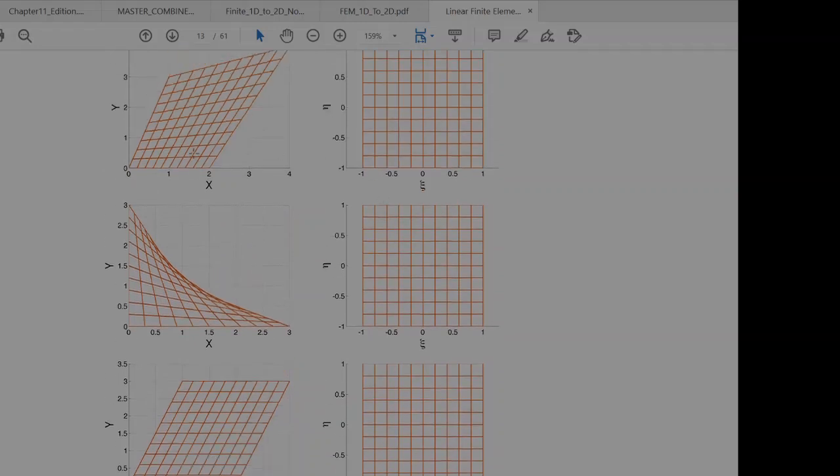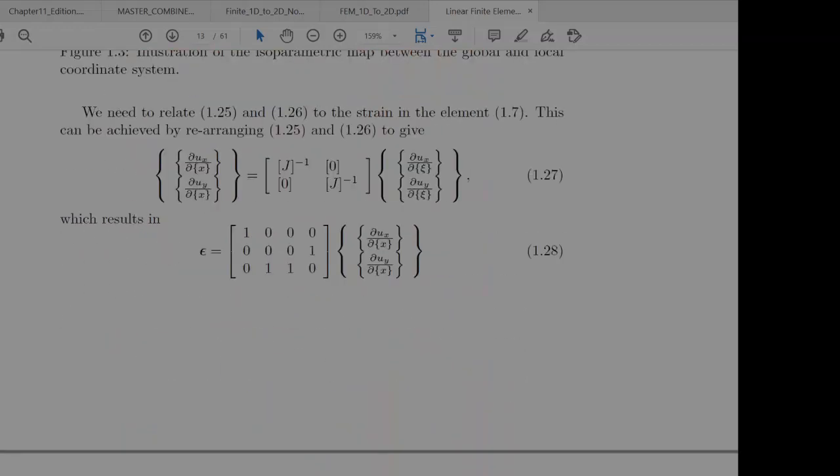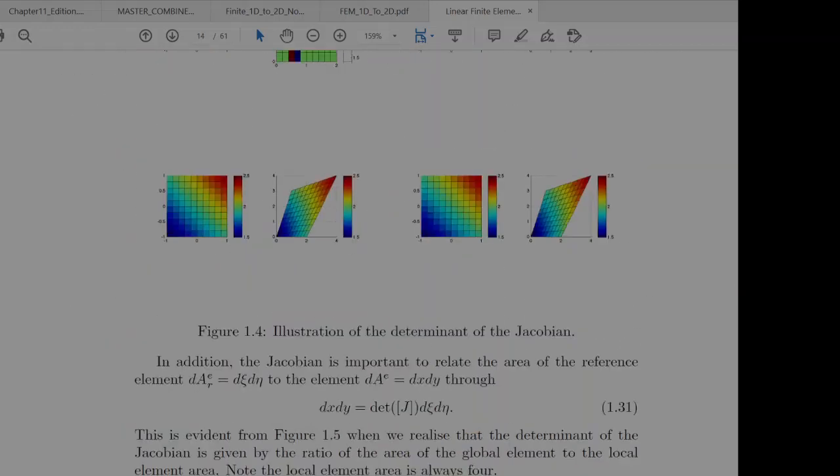Here you can see severely non-constant Jacobians, and this non-convex element is a disaster. You can see the chaos that's ensuing there: non-uniqueness and all sorts of stuff. You can't even tell which point maps from here to here. So that breaks down the mapping completely. Okay, then let's